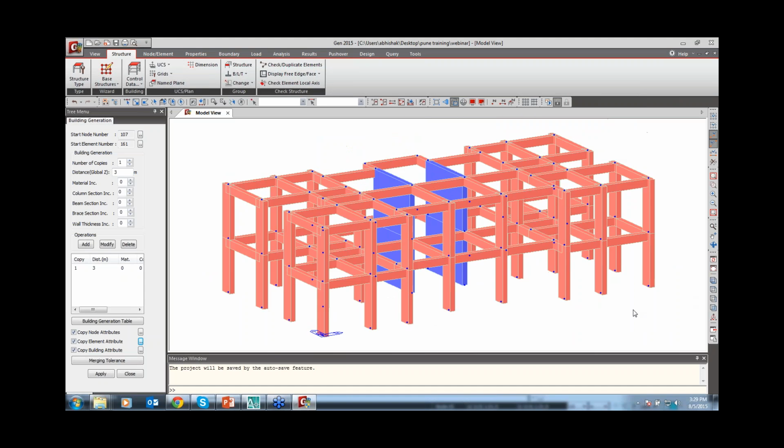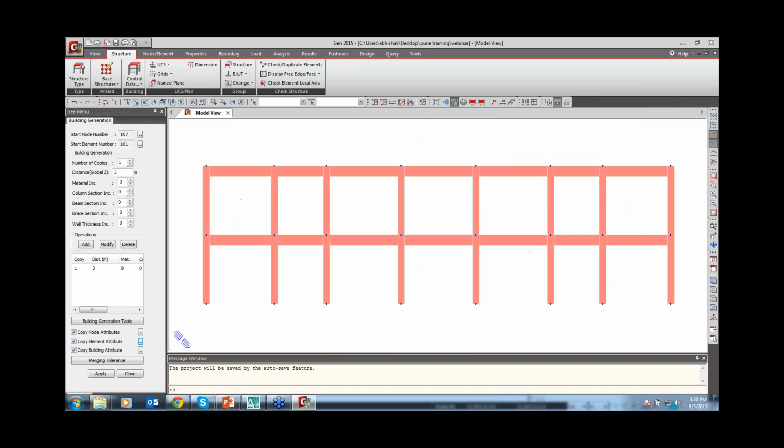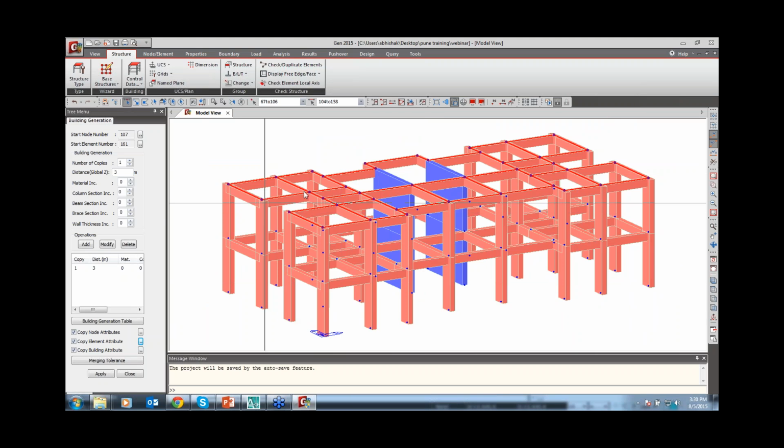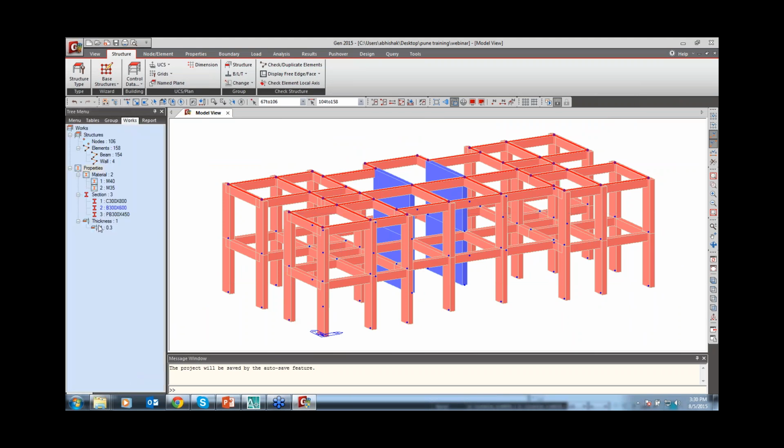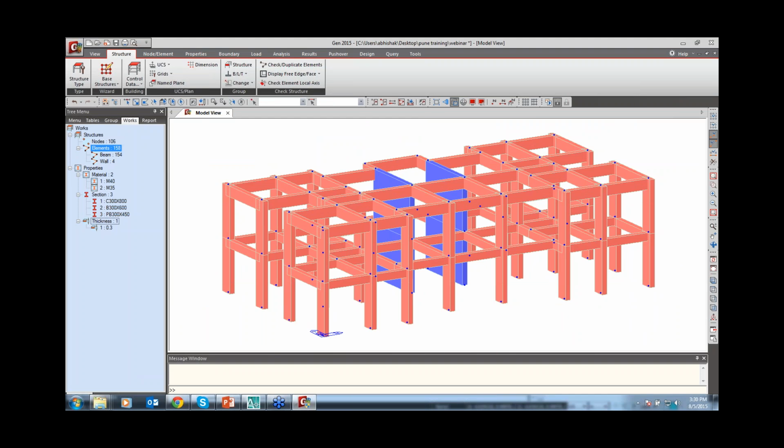Now for this above section, I just click here and select only the top view. Now you can see my entire beam is selected. Now I just change this size to 300 by 600. Within a few seconds, just select the element and from the tree menu you just click that property and drag it to the screen. You can change the particular property. No need to go to another software point. And whatever things you want, you can see here.